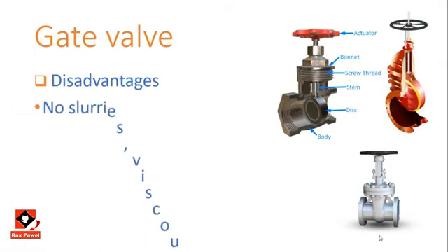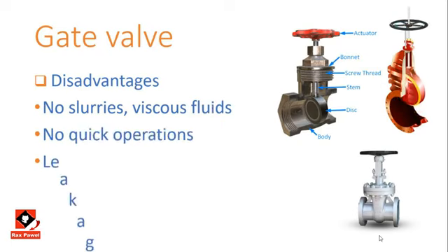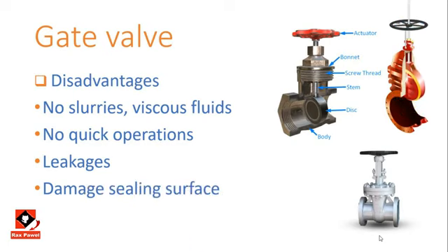Disadvantages. Gate valve cannot deal with slurries or viscous fluids and cannot operate quickly. Sometimes leakages may occur due to load, and sealing surfaces get damaged due to friction.